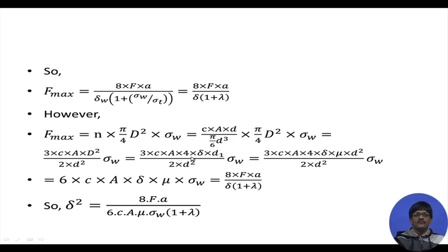and what is this 4 into d d1 into delta? Oh, that is coming from d square. D square is simplified and put here, and 2d square was already existing, and therefore we can still remove the expression of d1. d1 we are replacing by mu into d square. Please remember, d1 is the lobe diameter, and d is the grit diameter, and they are related as d1 equal to mu d square, and therefore we have replaced that.